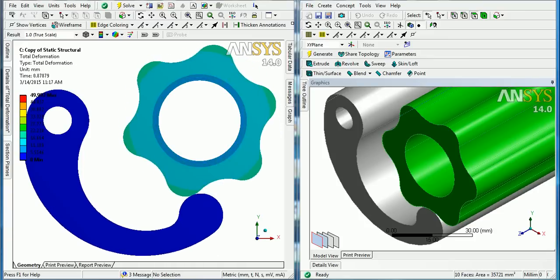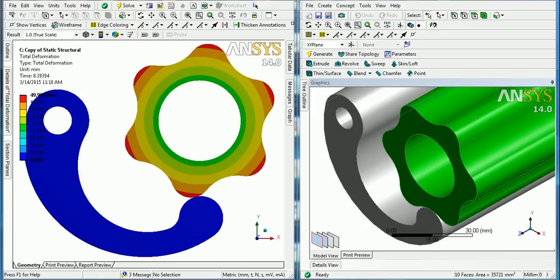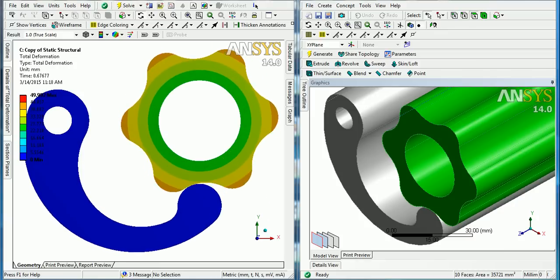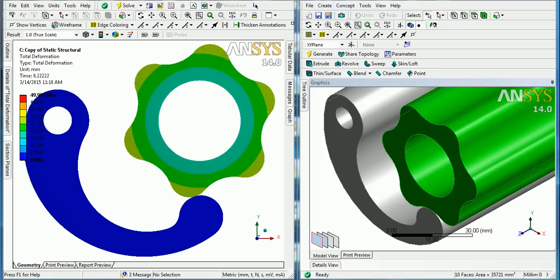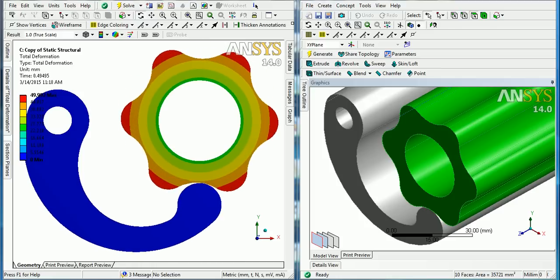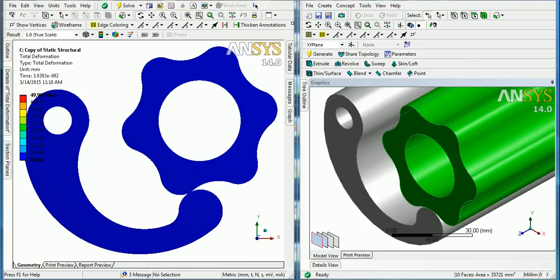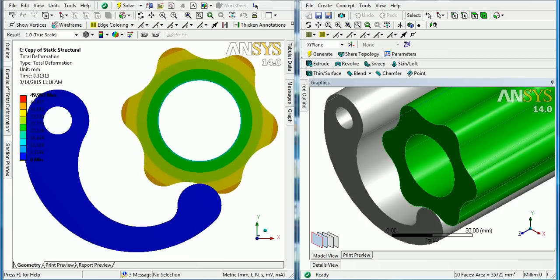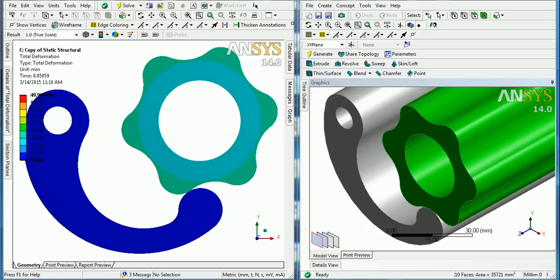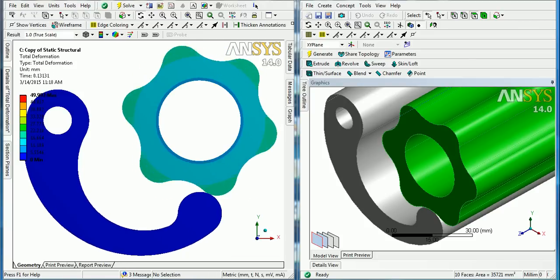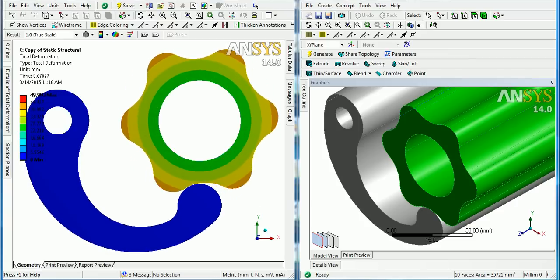This video is the demonstration of plane strain analysis. A mechanical structure can be treated as a plane strain problem if the strain along the z direction, or normal to the xy plane, is 0 and the shear strain in the xz plane or yz plane is assumed to be 0.